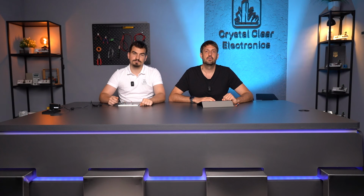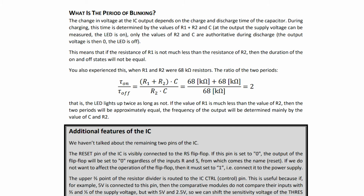This means that if the resistance of R1 is not much less than the resistance of R2, then the duration of the on and off states will not be equal. You also experienced this when R1 and R2 were 68 kΩ resistors. The ratio of the two periods can be calculated by the following formula, and by substituting the numbers, the result is 2. This means that the LED lights up twice as long as it doesn't.